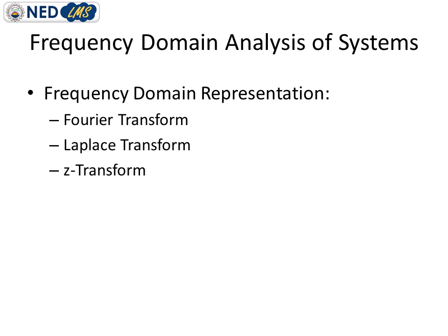But the Laplace transform is a more powerful tool as compared to the Fourier transform, as it transforms the signal or the information into the frequency domain, and it will tell us two things. First one is the frequency response. Obviously Fourier is also telling us the frequency response, Laplace is also telling us the frequency response. The additional information which the Laplace tool is providing us is regarding the system stability, which is very important to analyze any system.